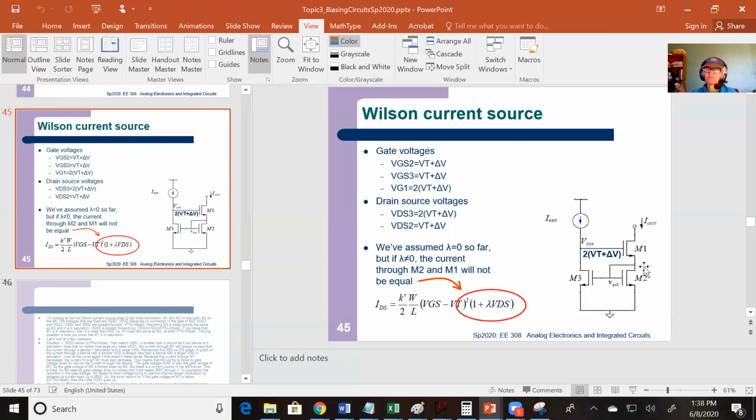But Wilson said, okay, well, let's do this. And I'm going to diode connect down here. Does anybody remember the resistance of a diode connected transistor? From all three terminals have the same resistance. 1/gm? Yes, so it's a super little resistor. So this actually, it's like degeneration, but with a resistor of 10 ohms or something.